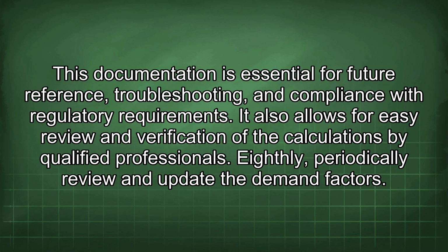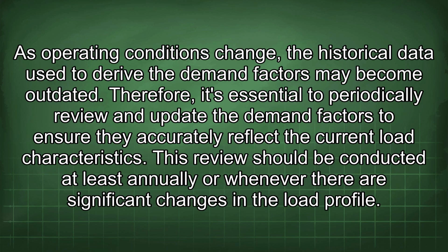Eighthly, periodically review and update the demand factors. As operating conditions change, the historical data used to derive the demand factors may become outdated. Therefore, it's essential to periodically review and update the demand factors to ensure they accurately reflect the current load characteristics. This review should be conducted at least annually or whenever there are significant changes in the load profile.